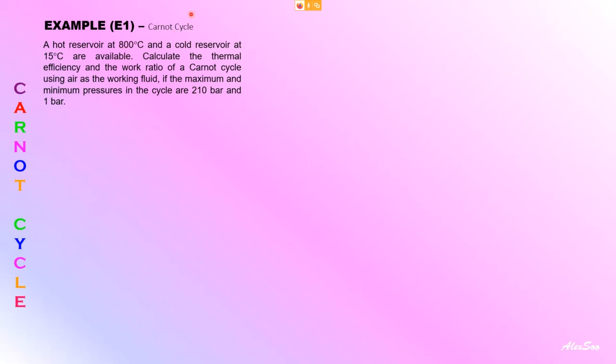If, let's say, for example, you are referring to a Carnot cycle, it consists of two isothermal processes and two isentropic processes. So here, these are the two temperatures that the question has given. So this is the high temperature and this should be the lower temperature. So if you were to put it in your TS diagram, make sure you convert it to Kelvin.